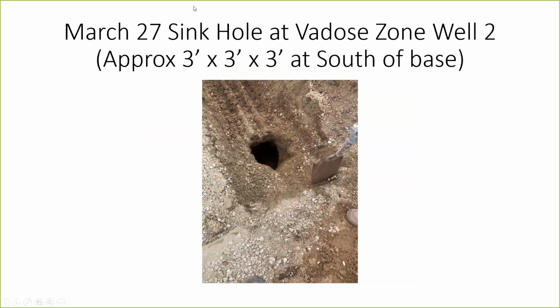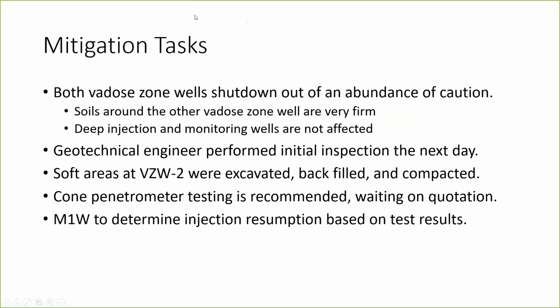Slide 4, please. So the next step forward: immediately on the 25th, when we found the sinkhole, we shut down both wells out of an abundance of caution. After we did the testing around the first well to create the area that we were going to backfill, we went over to the Vado Stone Well 1B at the other well site, and the soils around that well were found to be very firm.